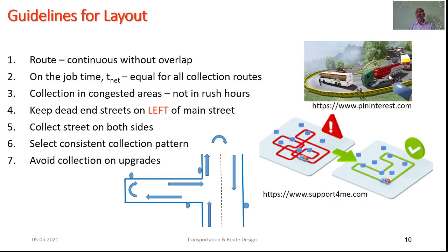On some difficult terrains, as well as in congested areas, the collection of this particular waste should always be avoided. As far as Indian circumstances are concerned, we travel on the left. So if the dead ends are on the left side, vehicle can enter within, it can serve the both sides of that particular road, can come back and it can resume its lane if these particular dead ends are kept on the left side.